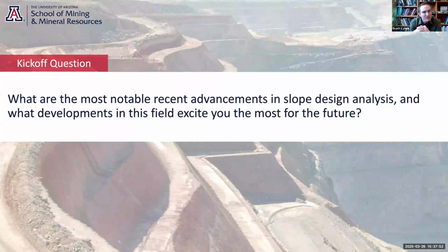And this is really important when we put these into our models, because you'll hear people say out there that there really haven't been very many pure rock mass slope failures. And I would say in my experience as well that is true, that 99% of the slope failures that I've seen when I go out to an open pit and do site tours and site visits, there's always usually some major structural component or some weakness or alteration component that goes along with the failure. So how we put this anisotropy into our model makes a big difference in the analysis. It makes a big difference in the factor of safety, and it makes a big difference in how we design the slope.